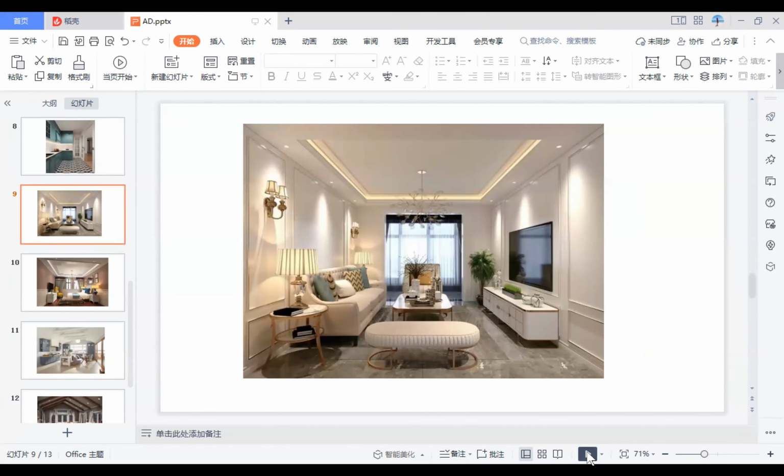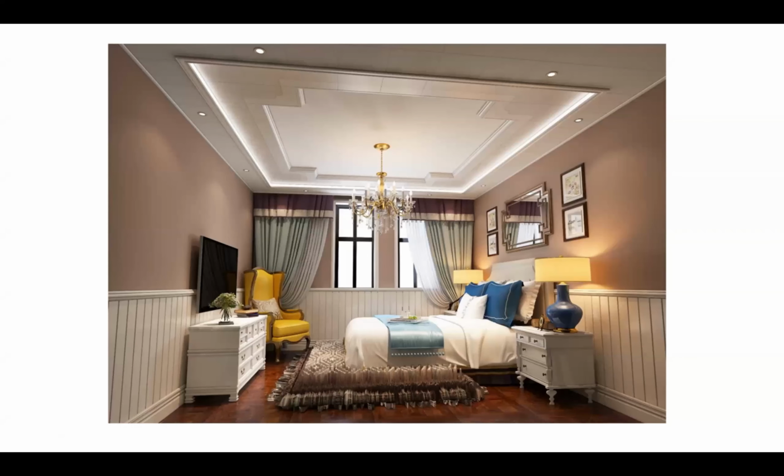For picture 1 and picture 2 are basically the same way to design the ceiling. In general, first, you need to draw the shape, no matter it's just a simple rectangle or the one we have in the middle. So the first way is to draw the shape. And the second way, you can set the extrusion to get them with different levels. So you can see the ceiling is suspended. Number 2, you can add molding, you can add paints or gusset plates or whatever to give them a texture, right? And then you can add molding, light strip, or the elevation paints. Okay, so this is how you make the ceiling.